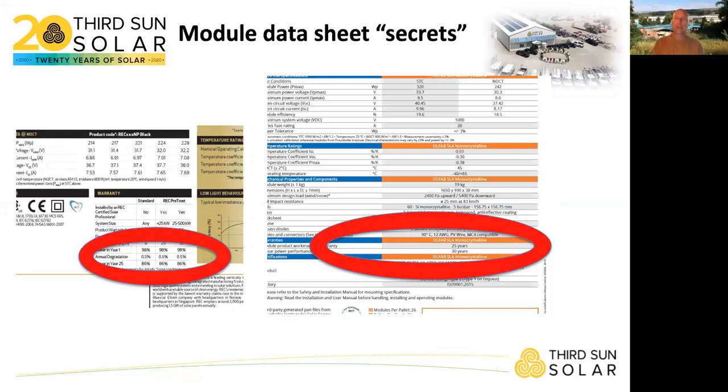That's one of the important things to look at. There's a lot of other nerdy stuff, and if there's any nerds in the audience, we can get into that. One of the other characteristics that we look at is the energy coefficient, or the temperature coefficient. Modules do better in colder temperatures, and as the temperature rises, they put out a little bit less power for each degree Celsius that the temperature rises in the operating conditions. So that's another way that some modules outperform others.